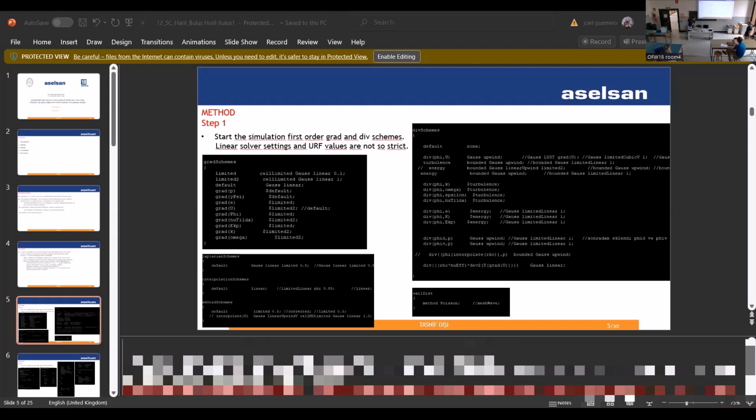So these are the CP distributions over the sections, and they conform well with the experimental values. This is the pressure contour, taken from the preview. This is the well-known phenomenon: the lambda shock wave is also captured. You can see that.